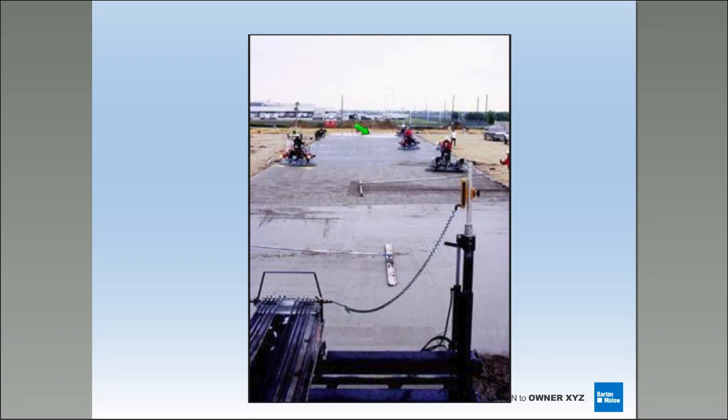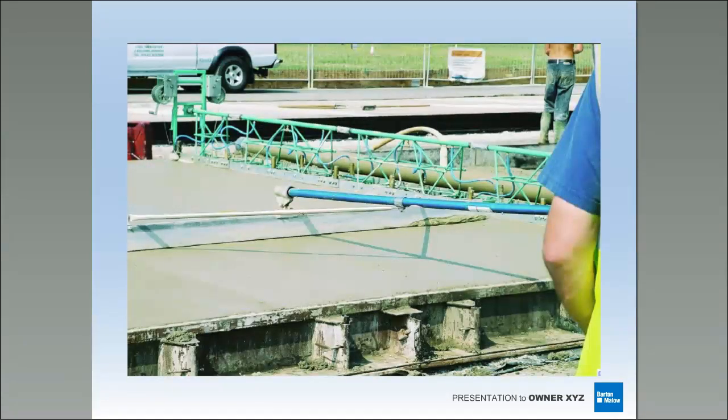But what I don't like about this picture, guys, is I have no walls. I have no roof. In my opinion, I would not do this unless I was forced to. But again, it shows you the method you should be seeing at the frequency you should see it, right? Again, this is what I was talking about when we were talking about moving that cream layer. This is a prime example of it. Looks really flat, but to get it as flat as he needs it, he's going to move that cream to where he needs it. So in theory, or in fact, you're skimming some of that cream off that's covering the aggregate, so when you go to polish it, you're going to hit that aggregate very quickly.